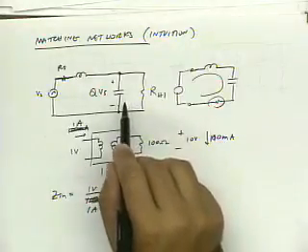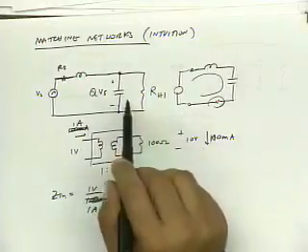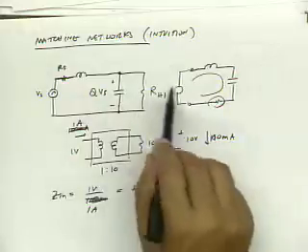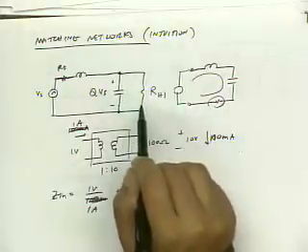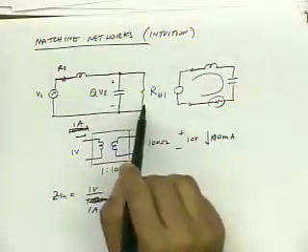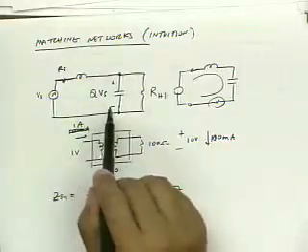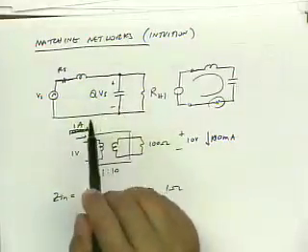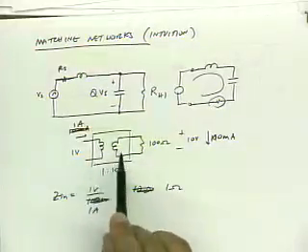So the current that I can drive this with is 1 over Q times smaller. So the net effect is that I've decreased this by a factor of Q squared. I think I'm getting things wrong here. But the important point is that the reason an L matching network works is because it can boost voltages and currents by a factor of Q, just like our transformer does.